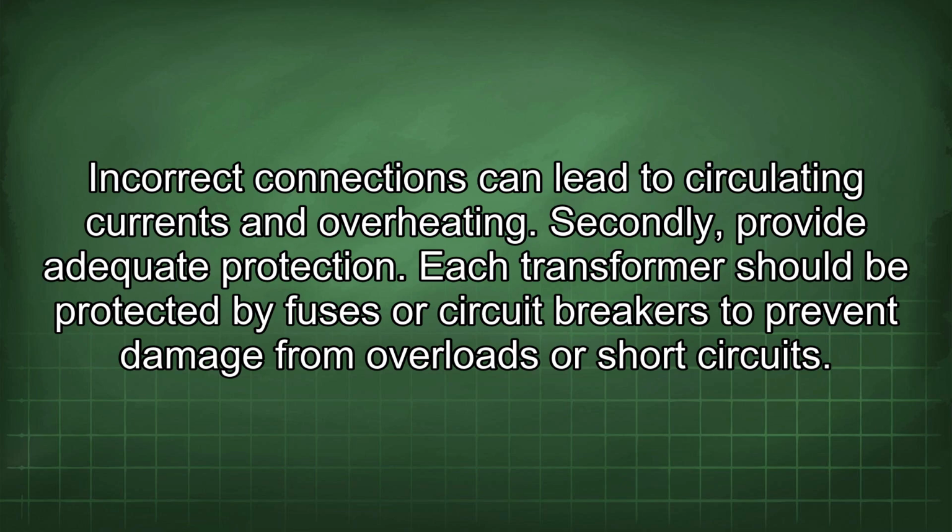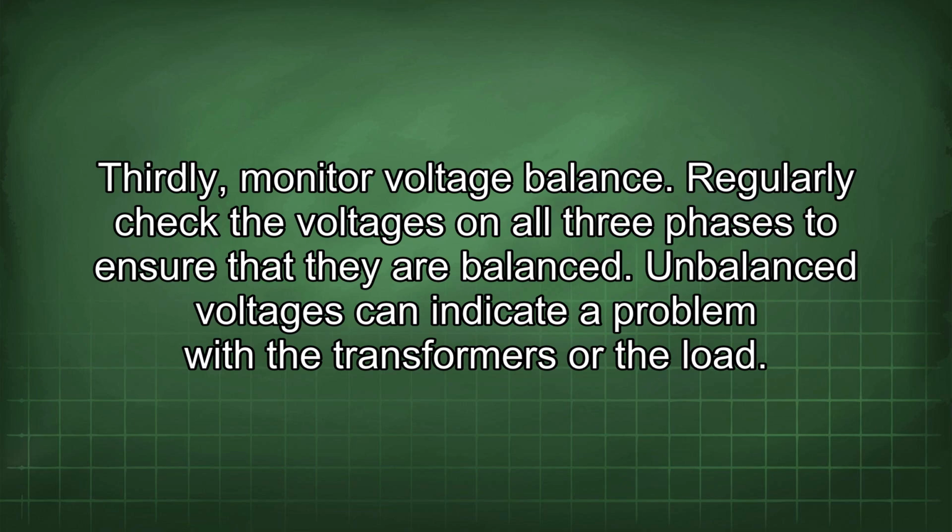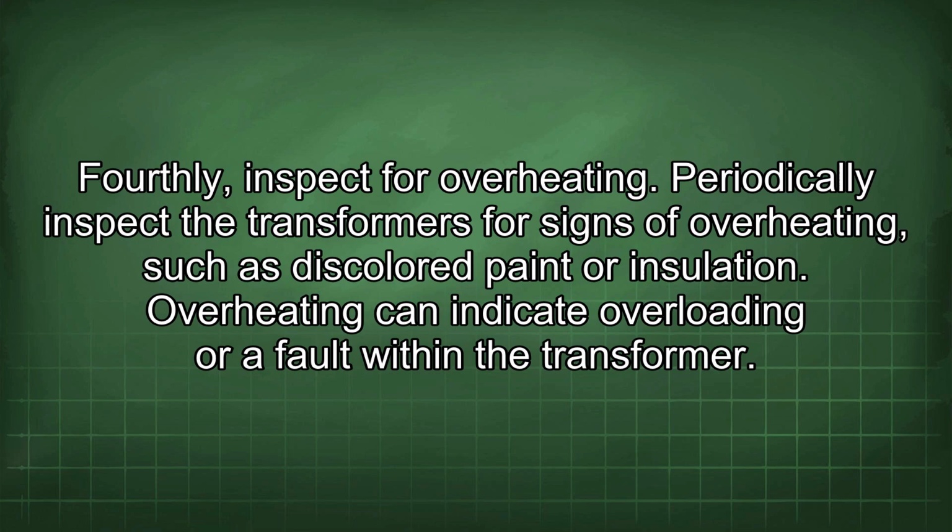Secondly, provide adequate protection. Each transformer should be protected by fuses or circuit breakers to prevent damage from overloads or short circuits. Thirdly, monitor voltage balance. Regularly check the voltages on all 3 phases to ensure that they are balanced. Unbalanced voltages can indicate a problem with the transformers or the load. Fourthly, inspect for overheating. Periodically inspect the transformers for signs of overheating, such as discolored paint or insulation. Overheating can indicate overloading or a fault within the transformer.